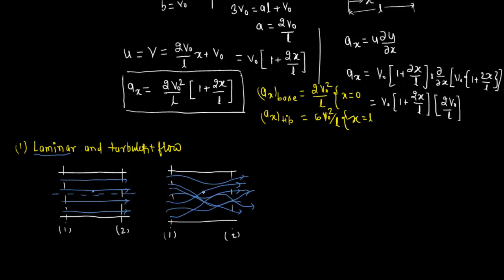But in case of turbulent flow, the particle is moving along this line but also showing some up and down motion, moving in the upward direction and then down, similarly in these velocities or layers. So in this case there are transverse or fluctuating velocities, and intermixing takes place. This type of flow pattern is defined as turbulent flow, and the other is defined as laminar flow.